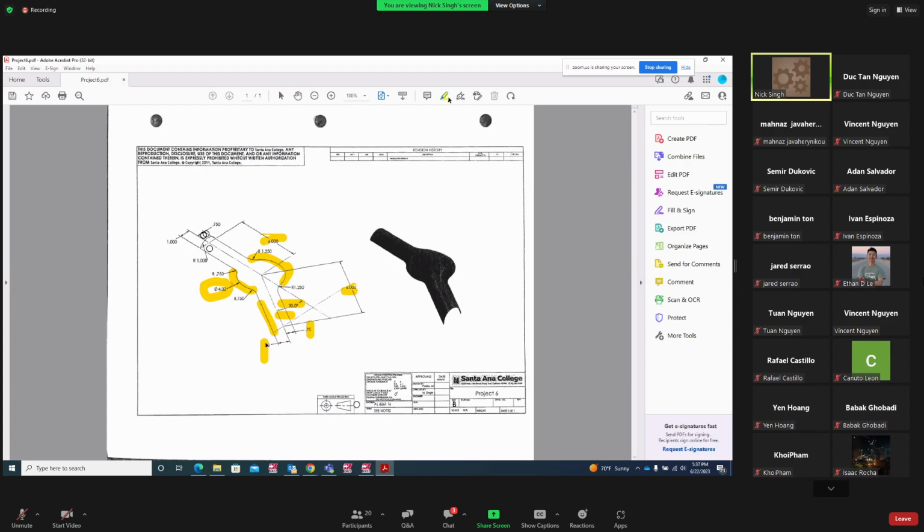So let's do this. Construction plane top, we're going to create one line from the center to here. That line is going to be 6 inches. Then we're going to offset that line 750 and 1 inch. Then we're going to create another line from the center, offset that 1 inch and 750, and that length of the line is 6 inches.